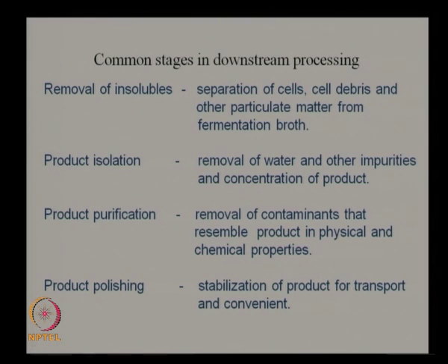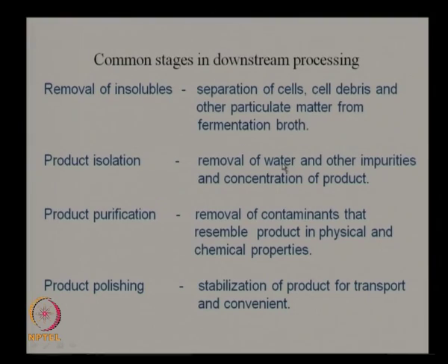Then the next step will be product isolation. The product concentration will be very small, 7%, 8%. So you need to take out the product from this large amount of liquid. So you may like to remove water. Water is present because most of the fermentation is done in aqueous medium, so there is plenty of water. You are adding salt, so you need water again to dissolve the salt. So there is plenty of water in your fermentation broth. So you remove water, and there are several impurities present, so you are removing the impurities as well, that is called the product isolation.